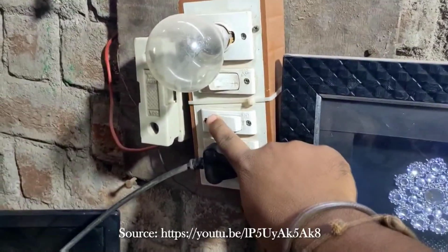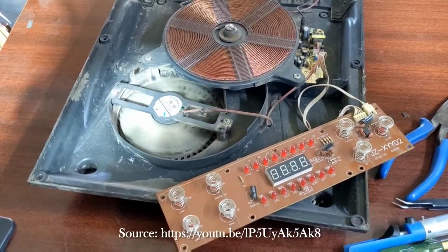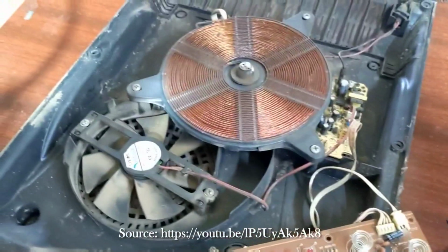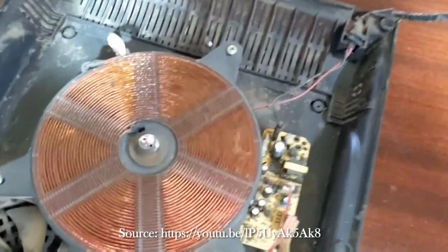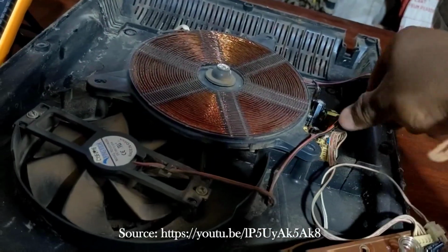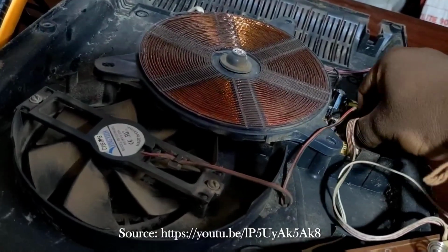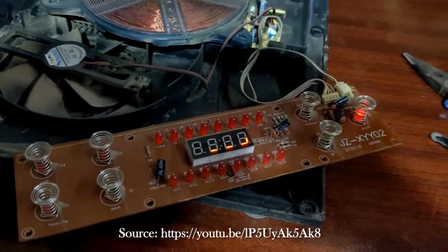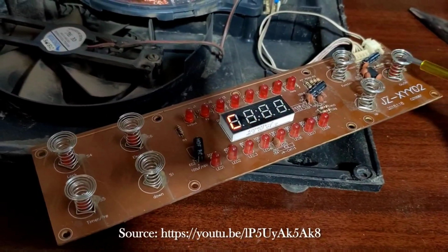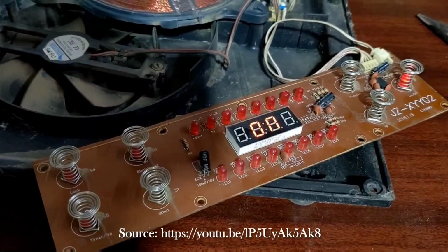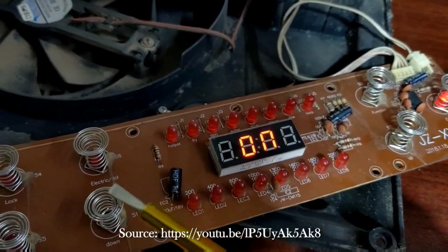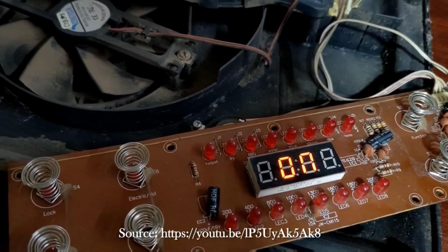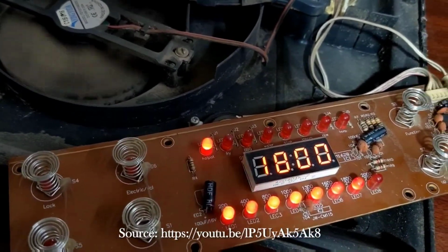When the power is on, the fan is moving, but there is no light in the display. There is no damage in the wire, but when the wire is touched, the display indicates some lights. This means there may be some loose connection issues or maybe some other problem. Now, when the power button is on, the display shows an error of E9.